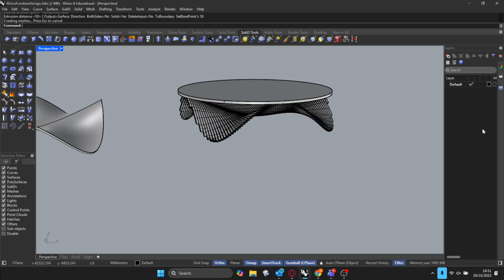In terms of degrees, unlike other surfaces in Rhino where you can specify degrees, with sub D, everything always has a curvature. So you need to understand the logic of how sub Ds work versus how a Rhino surface works. The way a NURB surface works is different from a sub D surface. A Rhino NURB surface has degrees of curvature, whereas sub D, because it can flow continuously, doesn't have to rely on those same mathematical parameters.